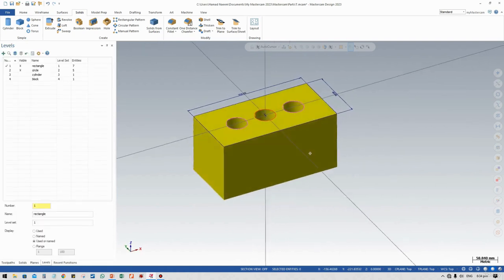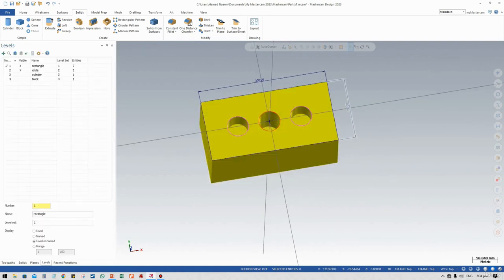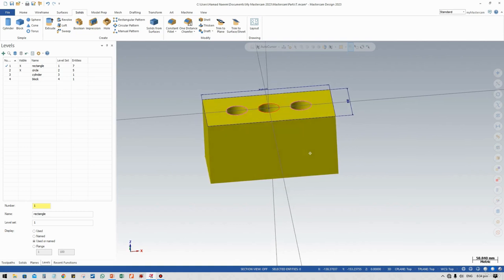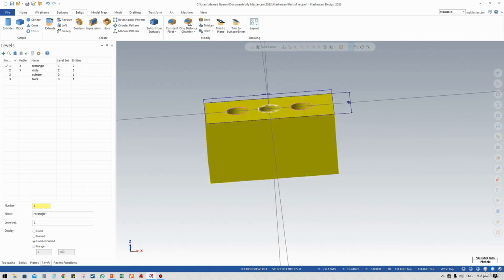So we have applied three circles commands here, and you can create a simple geometry. So this is how we can create a simple geometry using the extrude command. We have other commands also. This is the revolve command, this is the loft command, sweep command, and some boolean and impression and hole commands.